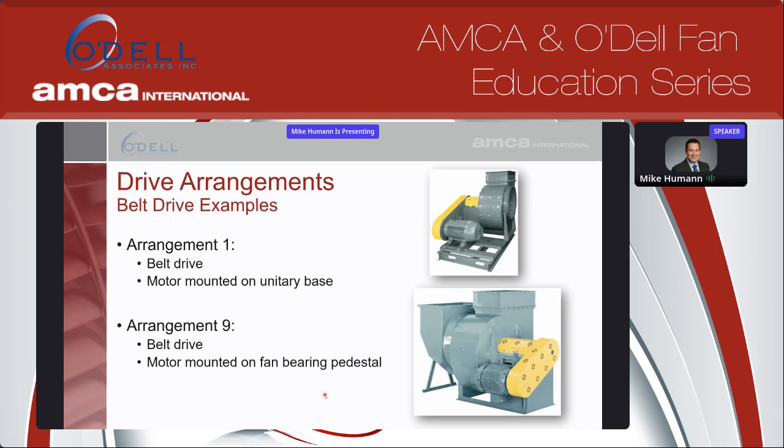But with these, you do have a lot more components than a direct drive fan. You have belts and sheaves, and on the bearings you're going to have some belt pull there. So that certainly can change the life of fans.